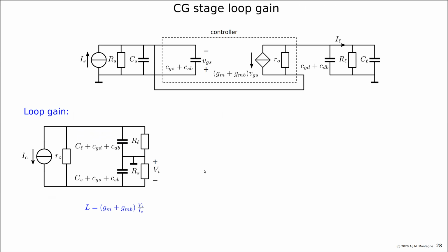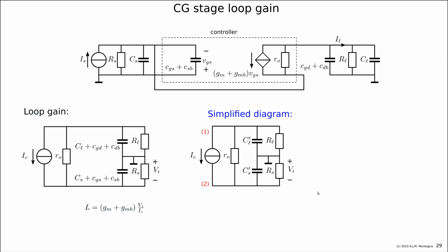The loop gain equivalent circuit, well, again, you select a reference variable, which is now gm plus gmb. They operate together. They are in parallel because VGS is the same as the gate-bulk to source voltage. So it's basically controlled by two controlled sources. Now we have more loop gain thanks to the backgate effect. So you can simplify this one as well, of course, and have this, including all the parallel connections,